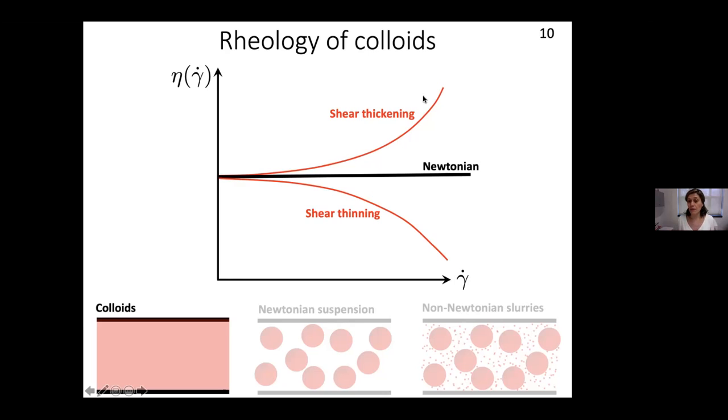So the example of shear thickening material is concrete. The example of shear thinning material can be mud, but also there is a possibility that the material exhibits a yield stress, meaning that below a threshold in a stress, there is no deformation, and above that the material deforms like a shear thinning fluid. Again, example is mud, because mud always exhibits a yield stress.